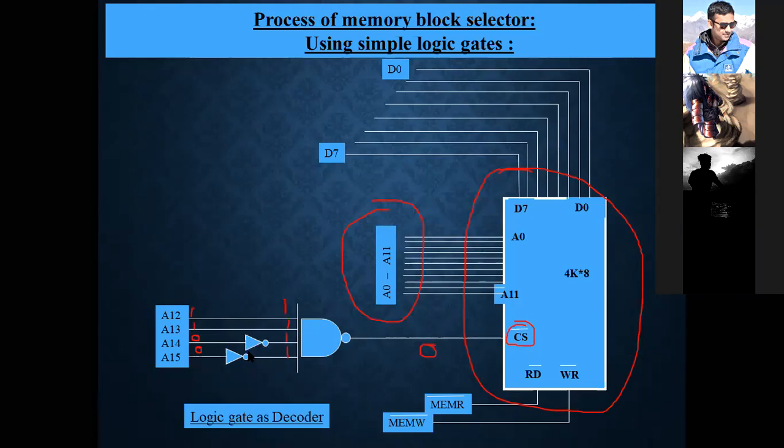So these total 16 bits are formed. What will be the range of this particular address? These lower bits can vary from all 0 to all 1, but the upper four bits are fixed because they are used for chip select. If we change this bit pattern, this RAM will not be active. So we cannot change these 4 bits in this interfacing. We will discuss some more interfacing in the next class also.